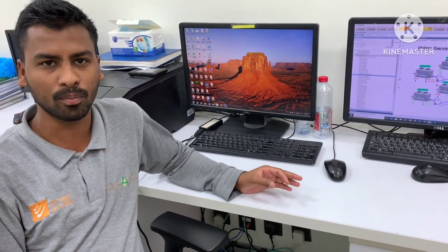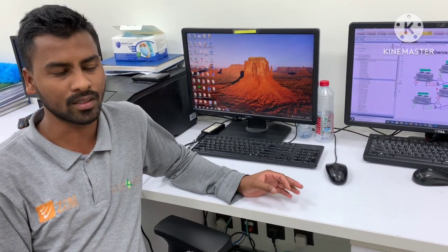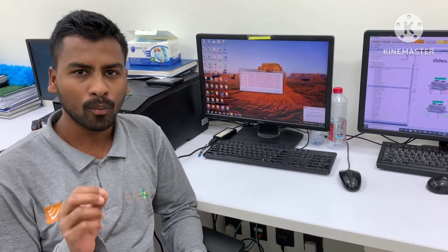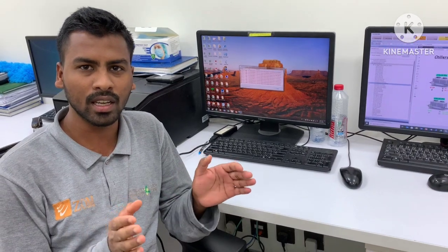First of all, you need proper documentation for the Modbus device. What type of documentation do you need? First of all, you need the register addresses. What is a register? In the Modbus protocol, every parameter or every detail or every point is stored somewhere in the storage, so we call it a register. Each parameter, like voltage, currents, loads and everything, is stored in a location of the memory, and we call that location a register.